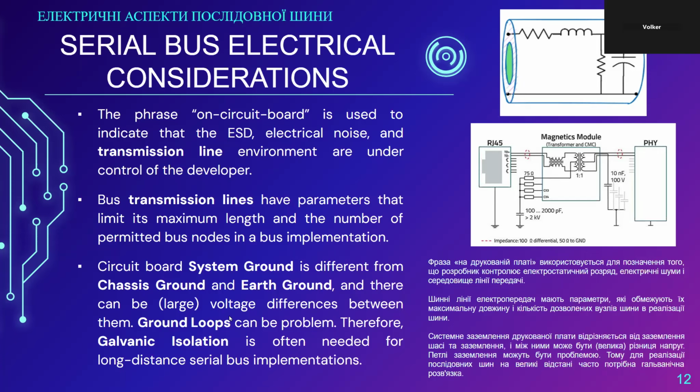So if your trace length on the circuit board approaches 30 centimeters, start thinking about transmission line effects. The effects are usually related to the routing of the trace, the ground plane under the trace, the closeness to other wires. It's just a rule of thumb.